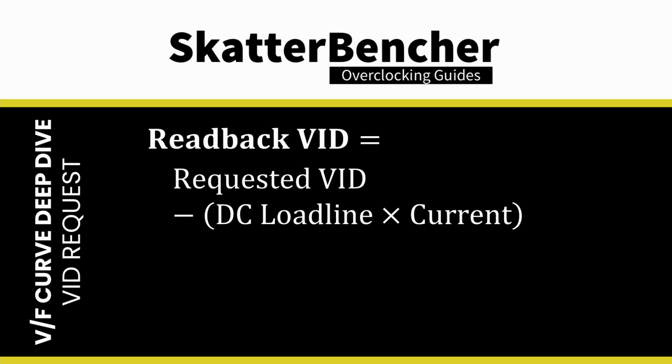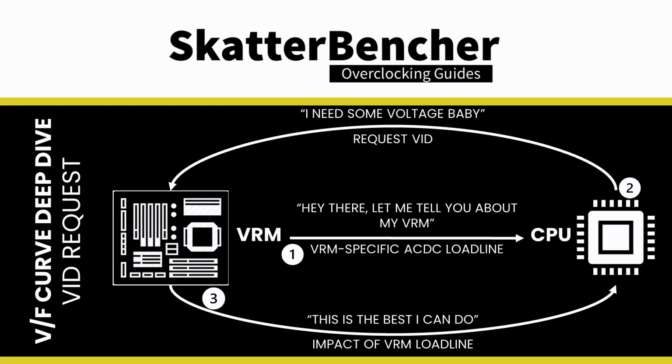The CPU will also read back the VID to check if it matches the requested VID. If the readback VID is lower than the base VID, then the CPU will dynamically increase the requested VID. In summary, the VF curve provides the CPU with a baseline VID. However, in order to request a VID to the voltage controller, the CPU takes into account a multitude of different parameters. This will be important when we try to figure out the baseline VID later on when we figure out the VF curves. In step 3, the VRM controller will output the voltage.